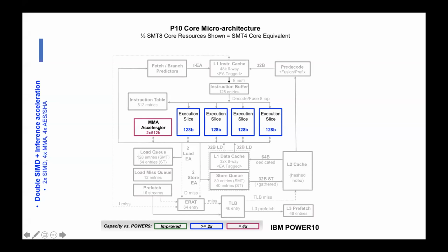And in parallel, you can also do, say, 2 MMA instructions every cycle, right? So you can generate 2 512-bit capability. As a whole, you cannot do all things in parallel, but certainly this along with 2 execution slices here can be done. And then there are some issue-level things that we have put in to make sure the bandwidth is balanced for the load and store ports as well. That way there is a huge FP compute capability.